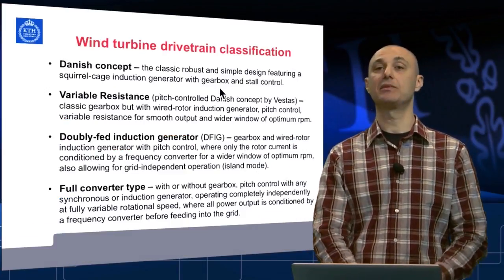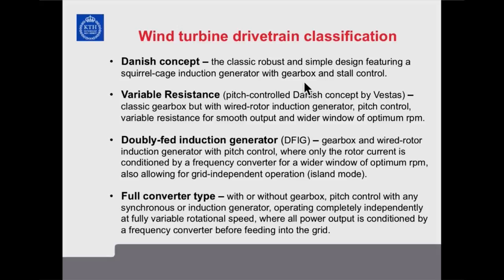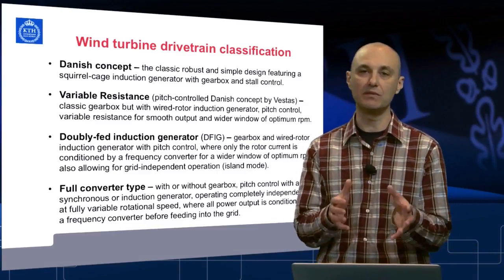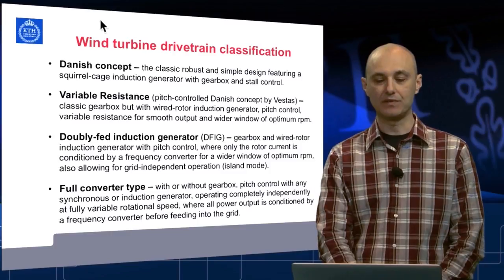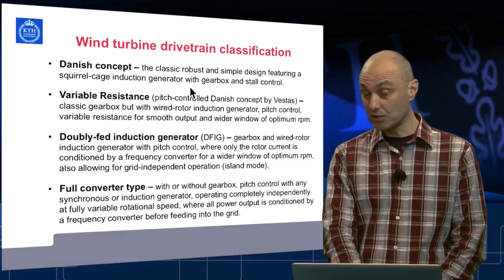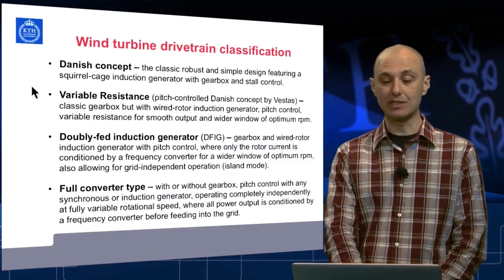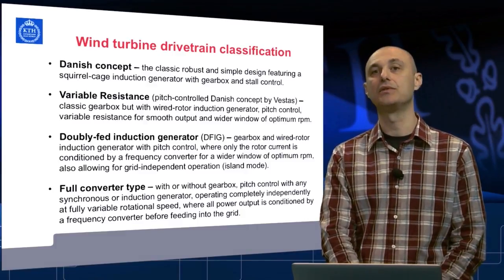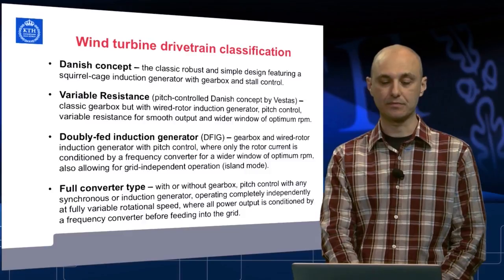The Danish concept, stall controlled, very robust, very simple. Best choice in the old days, usually using an off-the-shelf induction generator. Well, no components are off-the-shelf in wind turbines. All of them are tailor-made. But the Danish concept, or the stall controlled machine, is typically using the simplest generator you can imagine. That would be the squirrel cage induction generator.